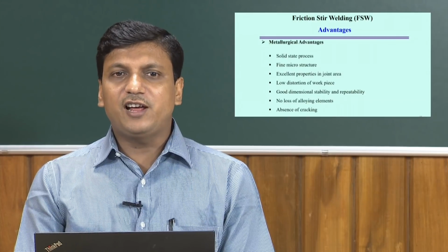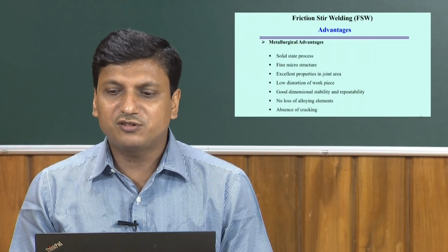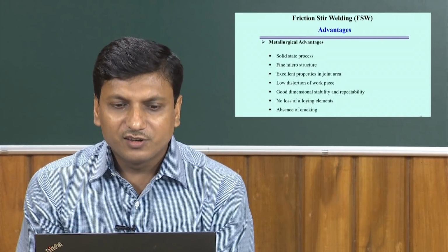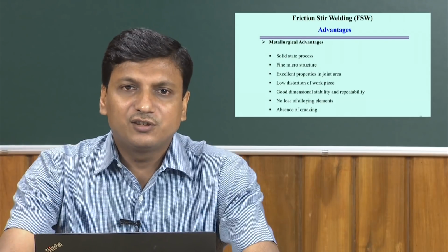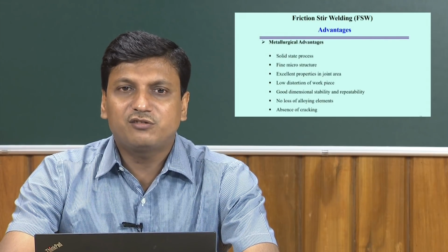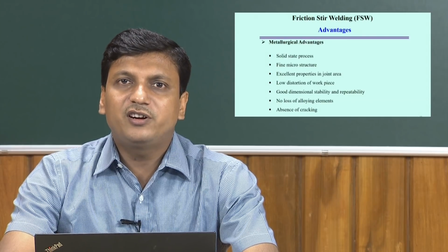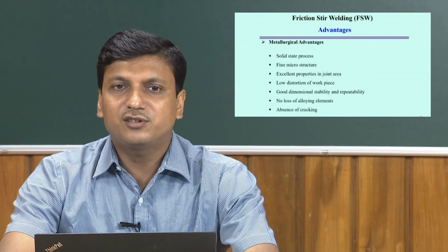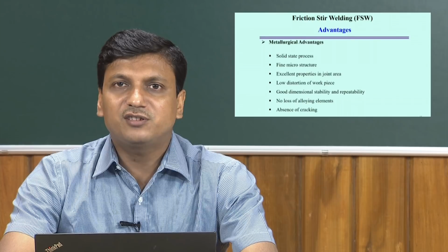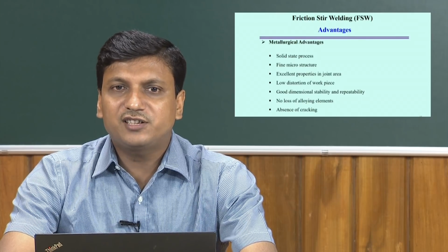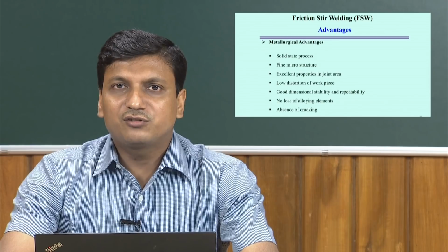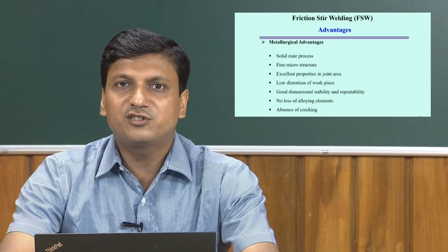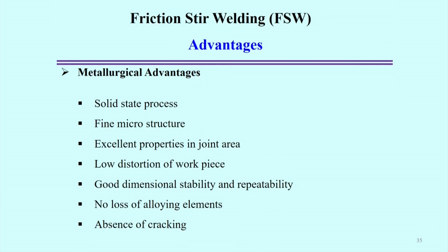But if we look at the overall advantages of the solid state welding process, we can summarize them like this. First are the metallurgical advantages. The first is that it is a solid state welding process, so it avoids any kind of complexity in solidification that may arise in fusion welding processes. All the phase transformation happens in the solid state. In that sense it is advantageous, because solid state phase transformation in the mixing, forming some of the intermetallics, all happens below the melting point temperature of either of the materials.